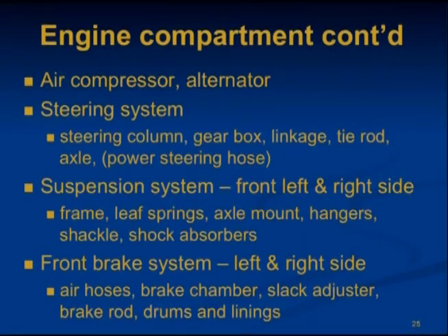Air hoses are secure on both ends and there is no audible leaking. Manual slack adjuster, the brake rod should not move more than 1 inch when pulled by hand. With the brake drums, check for cracks, dents, or holes, missing or loose bolts. For the brake linings, where they're visible, they should not be worn dangerously thin or soaked with oil.